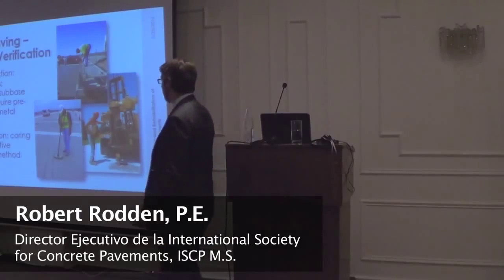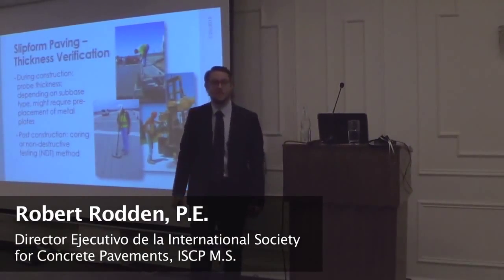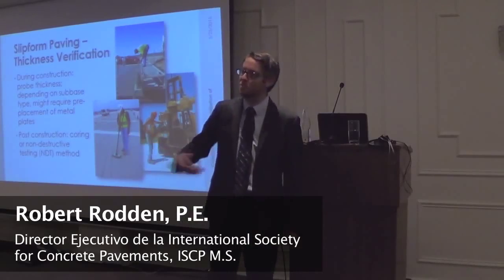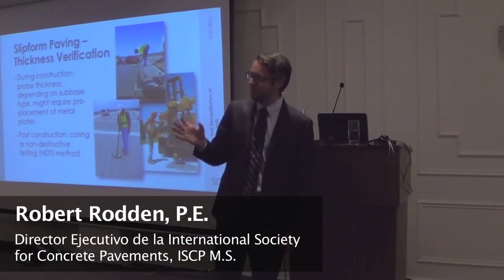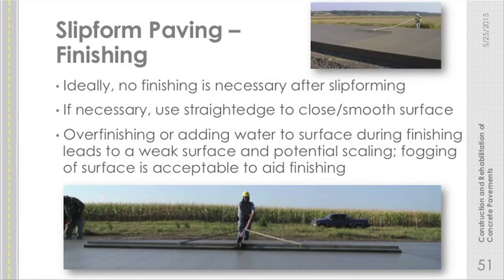Or if necessary, if we have to do something destructive, we'll core the concrete. In the US, we do that as little as possible, because now you've created some sort of non-uniformity, which is going to cause a difference in performance. So we prefer not to do that.